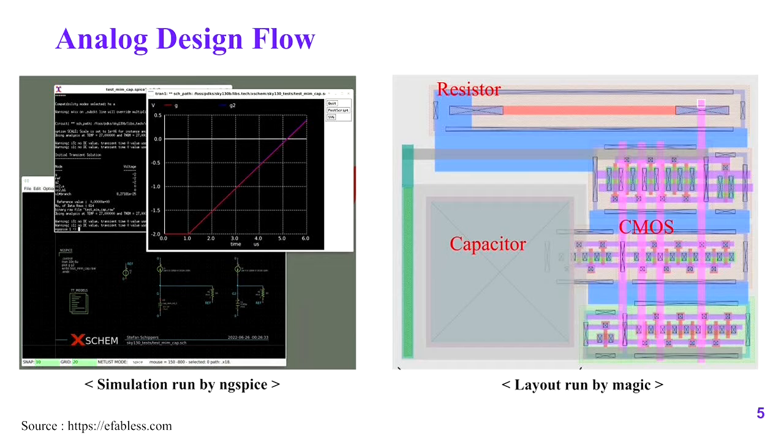We followed those tips, but for RF circuit design we really need a very accurate model of the inductor. So instead of using the ideal inductor model provided by Skywater, we gave up on the on-chip inductor and used an off-chip inductor. I know it's not an ideal environment and it's not desirable, but we decided it's good to just implement it. We plan to receive the chip this June. Once we receive it, we will use the off-chip inductor and wire bonding for the test.